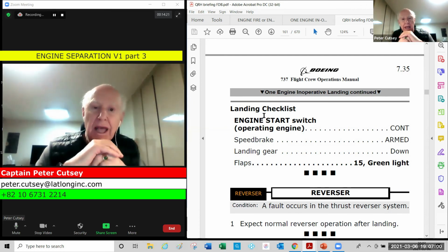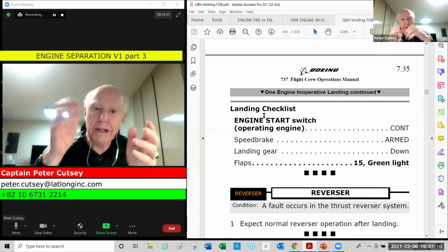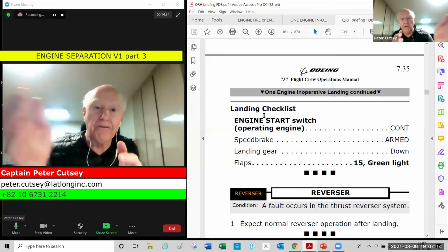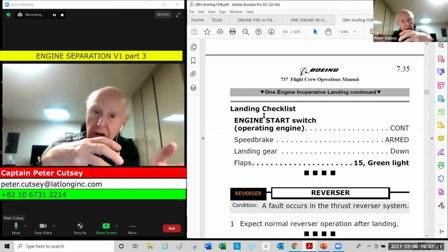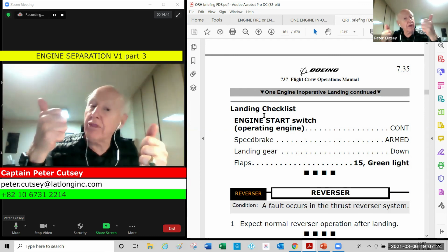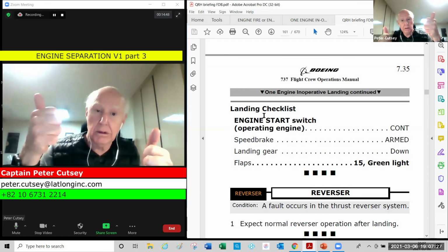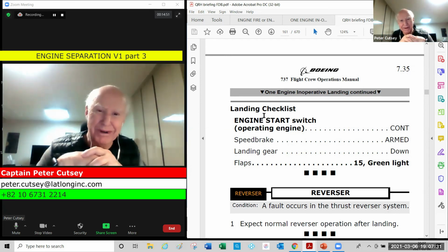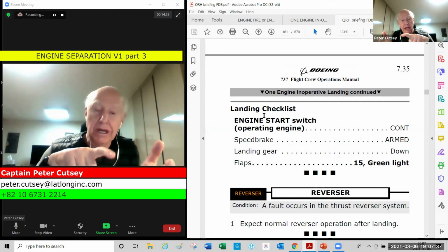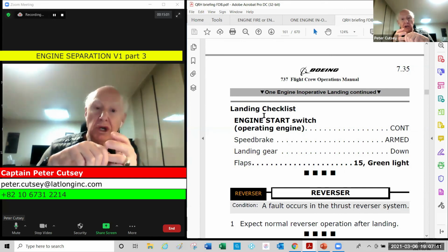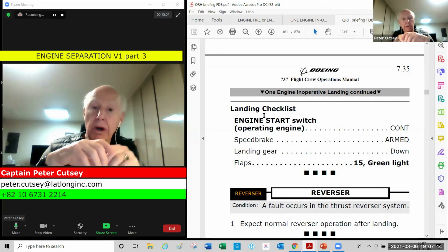It's quite extensive, and it's important that you have a good look at it and ensure that go-around thrust is set. Boeing's FCTM is quite correct when they say go around flaps 15, positive rate gear up for a normal, 2-engine operation, or go around flaps 1, positive rate gear up if you can get the gear up for an engine out operation. That is correct. Nothing wrong with the FCTM. It's perfectly right, but how you make those things happen is important. One of the most critical things in aviation accidents and incidents were pilots not knowing how to conduct a go-around, and especially a go-around from level flight. And that's something I'll discuss in a future briefing.